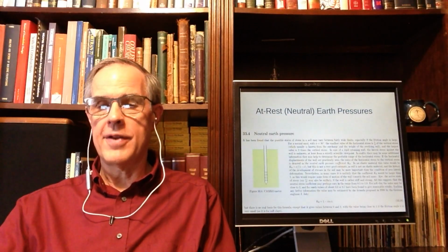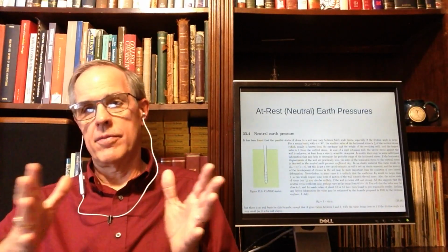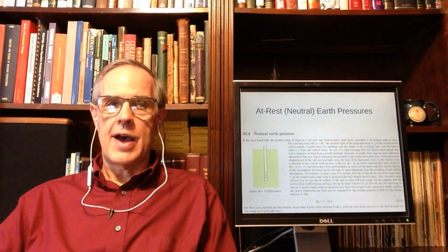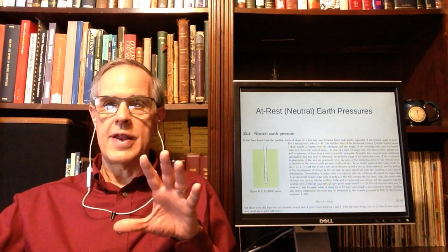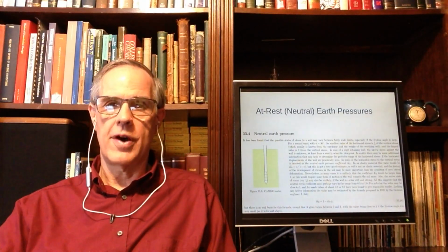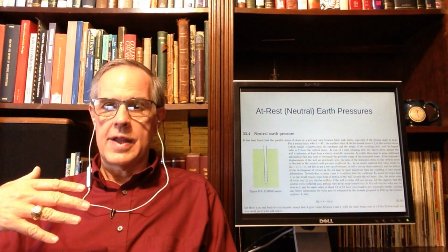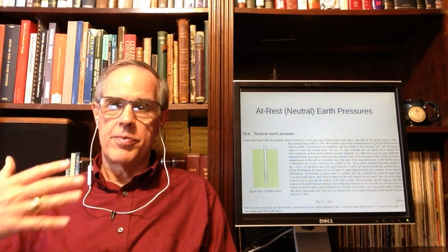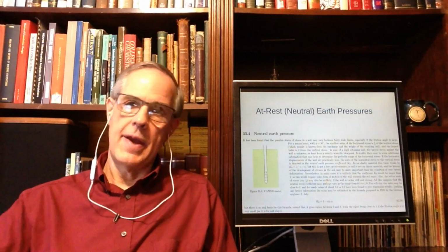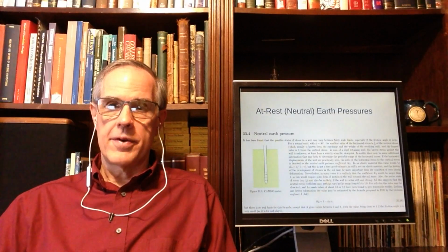Neutral earth pressures are basically the pressures when there is no movement of the soil laterally for any reason. And the most common state is soils without any kind of interruption. In other words, the semi-infinite mass that we talk about so often with theory of elasticity and other things. The normal expression of this is Jaky's equation, which is listed at the bottom of this page. And Jaky's equation is a purely empirical type of thing.